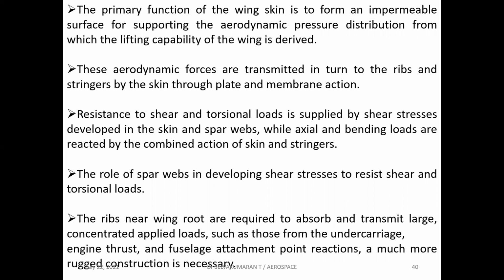Resistance to shear and torsional loads is supplied by shear stresses developed in the skin and spar webs, while axial and bending loads are reacted by the combined action of skin and stringers. The role of spar webs is in developing shear stresses to resist shear and torsional loads.